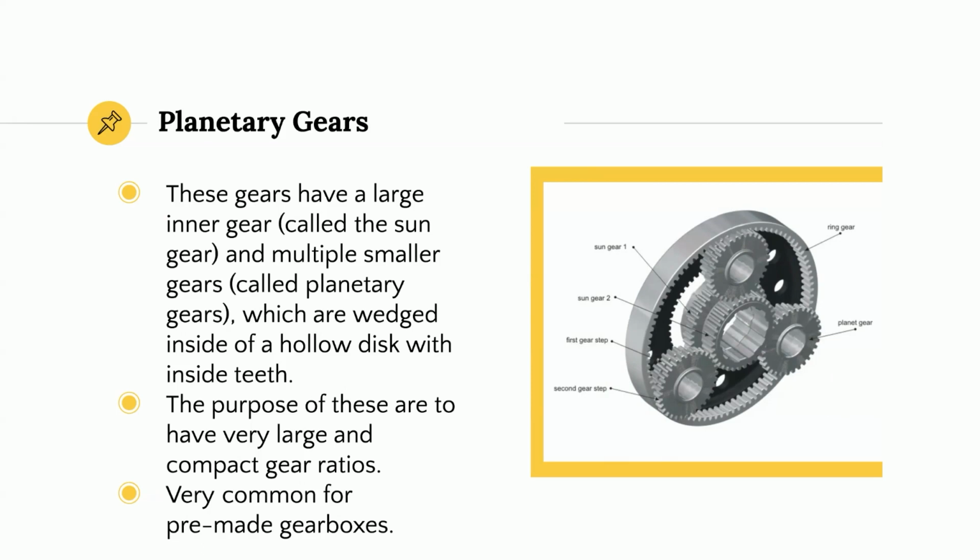Now the gear ratio between the sun gear and the planetary gears is the actual ratio between them. But if you just have one really large gear and a couple of really small gears, it'll be kind of weak. So what you want to do is have 3 smaller gears, and then you can layer them vertically so you can stack them and make really, really large gear ratios.